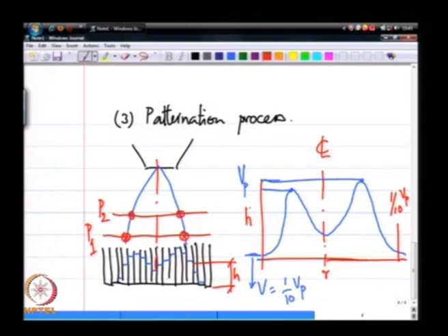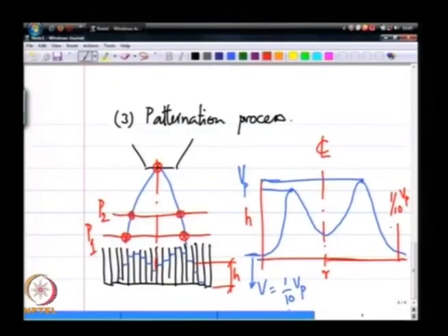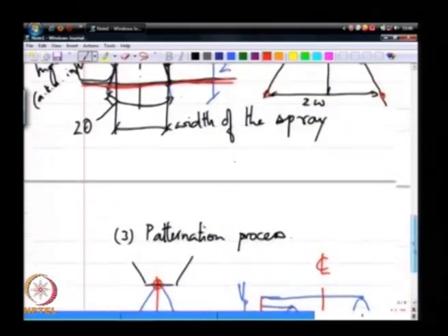So, it is the old spatial versus temporal measurement techniques, but for this particular spray characteristic that we are interested in, both of these give reasonably the same answer. Size velocity correlation is where spatial and temporal measurements are not independent, whereas when it comes to spray cone angle as an entity, it gives approximately the same values. Even if they are not quantitatively the same, the techniques are very close, they yield very similar results.